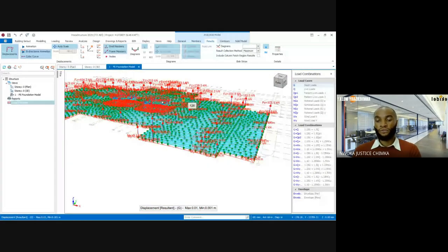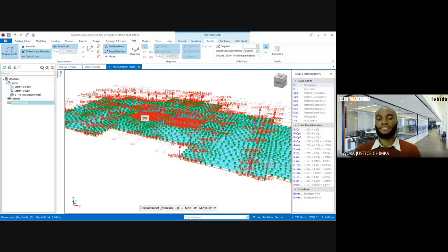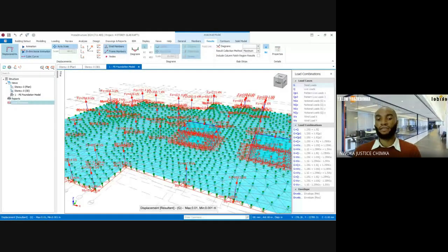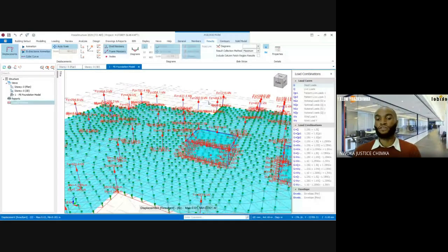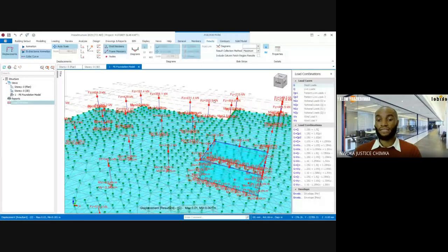On this, the next thing you do is to apply the contour. You can see the forces from the vertical members, the forces for each of the columns or walls. These are the axial loads beginning from the last story, which is the 8th floor, down to the foundation. So these are the reactions. To apply the contour, click on this contour tab here.